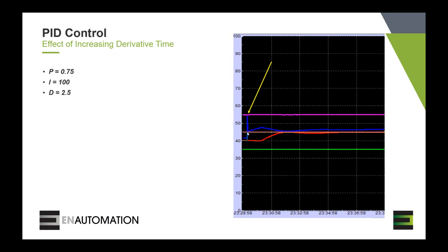in the set point results in a step change in the error, but after it makes that step change, the error is constant. So the rate of change of the error term becomes 0 again, and the derivative function dies out. And then just the proportional and the integral takes over. So other than that initial spike to the change in the set point, the derivative has very little response on the rest of the process.